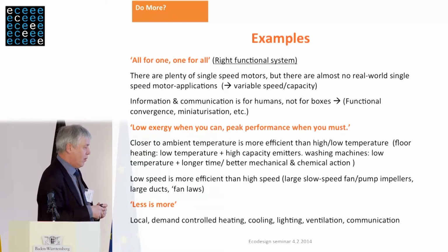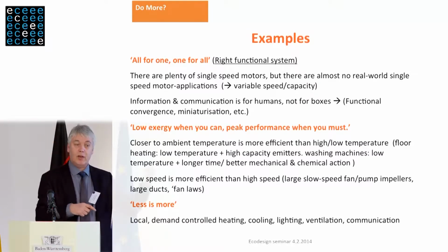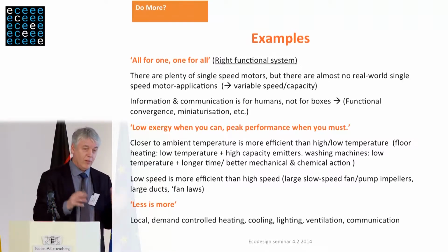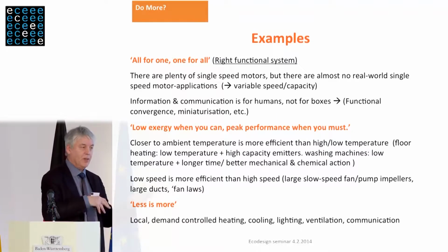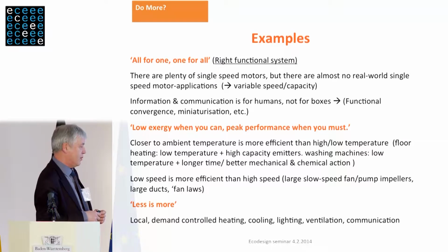I forgot here the fans. You have usually a choice between a small fan, which is running at high speeds, or a large fan running at slow speeds. If you have the space to do it, choose the large fan with the slow speed instead of the small fan with the high speed. It's physics.